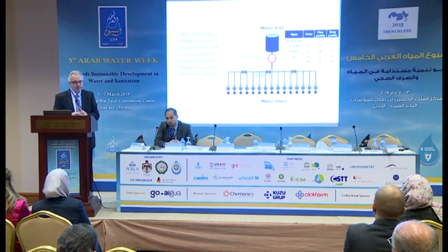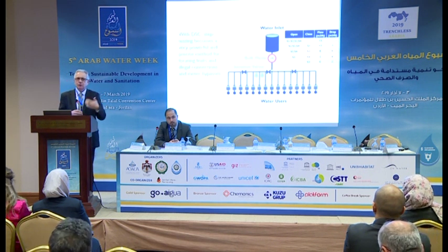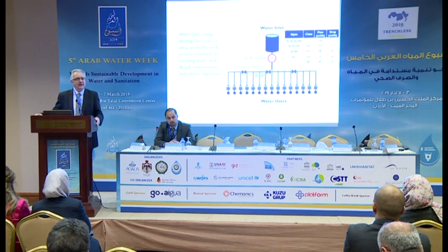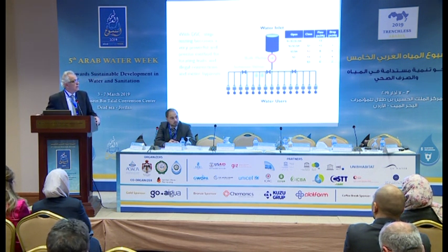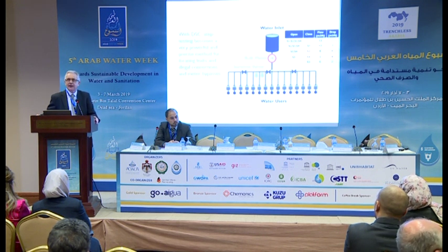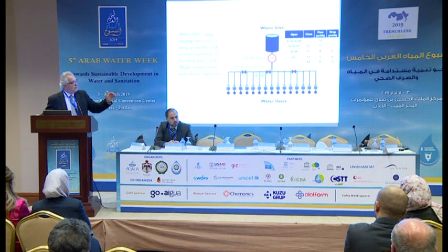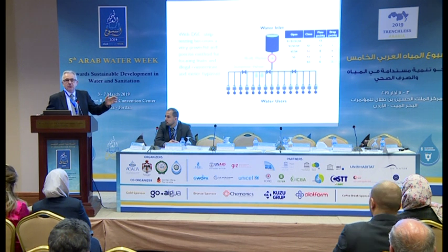And of course, we can use a very traditional method that I used at least in my early days in water management systems, step testing. Step testing is a great way of finding out where to start your leakage activities. You can see from this graph that we have 4 steps, S1 to S4.